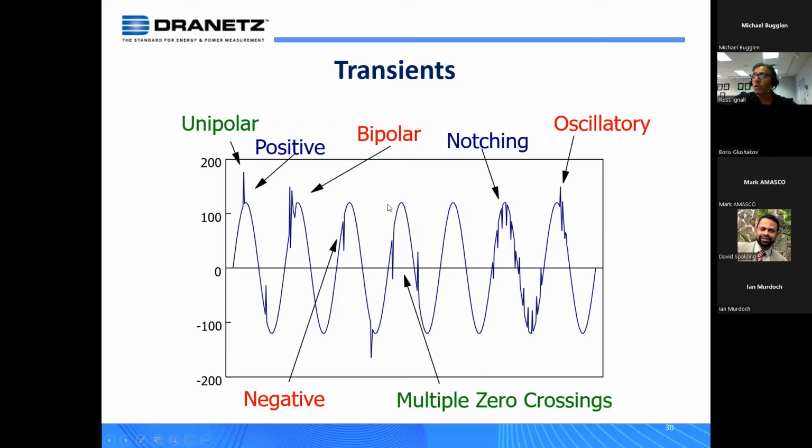So here's a unique transient. This is a negative transient that can also create frequency counting issues, which is very unique. There's still circuitry out there, such as low-end digital clocks, that counts frequency by looking at zero crossings. So as an example, we have one zero crossing going from negative to positive, a second one here, a third one here.